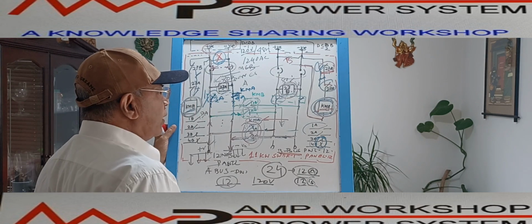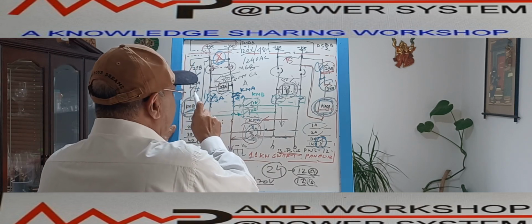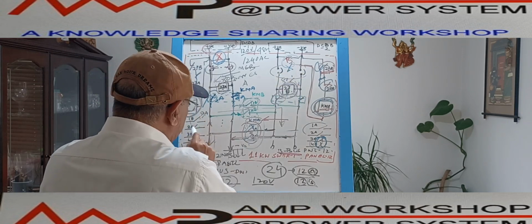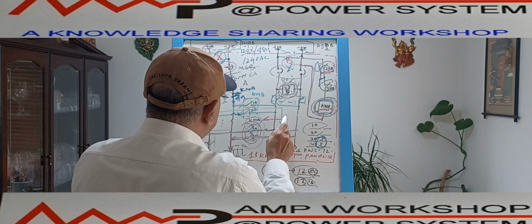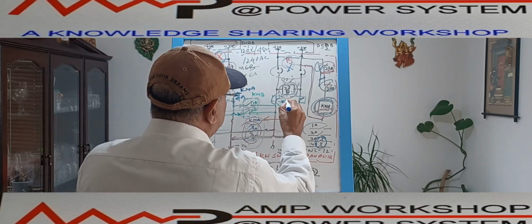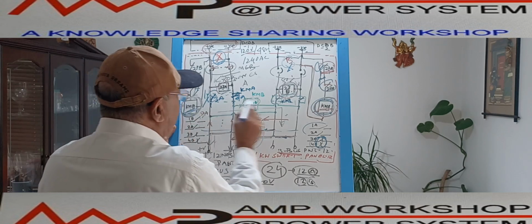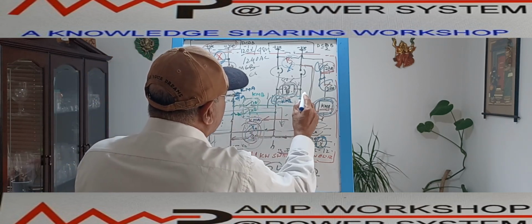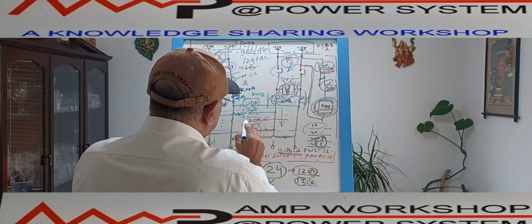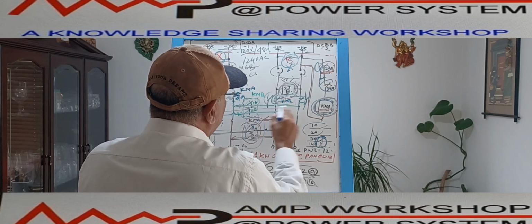So power will be flowing, but the moment the KMA power supply fails, power will come from KMB to over here by this path. At the same time, this KMB NC contact, okay, will stop the backflow, because the moment KMB is energized, this NC contact becomes NO. So in case of failure of this power supply, this contact becomes NO and this contact becomes NC, so it will give the power and stop the backflow.